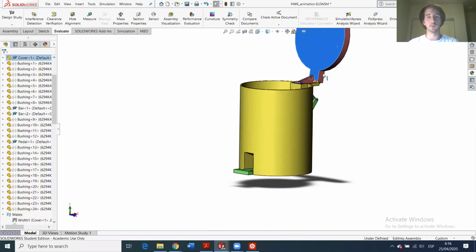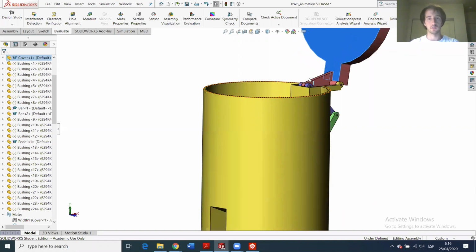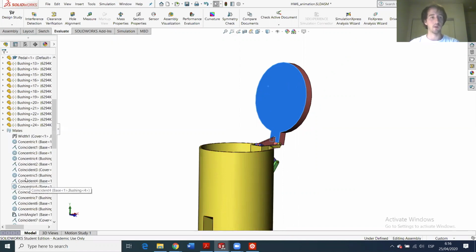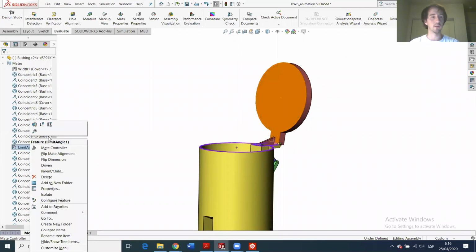Either the maximum or the lower, because with the motor, we will tell the mechanism to move from here to here, and we will need to specify how much we want it to move. So if we say 100 degrees and we start from an intermediate position, it will go from here to here, and it will collide with the cam. So we want it to be in the extreme position. And now when it is in the extreme position, we delete this relationship.